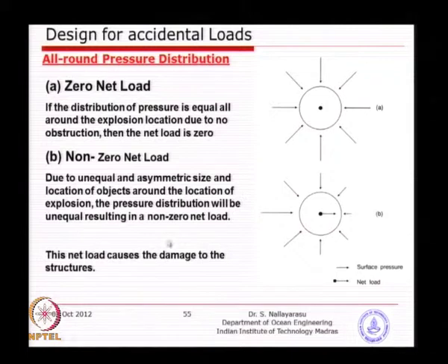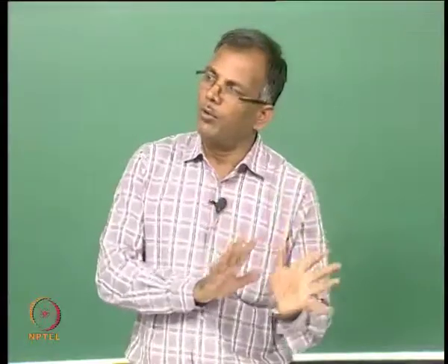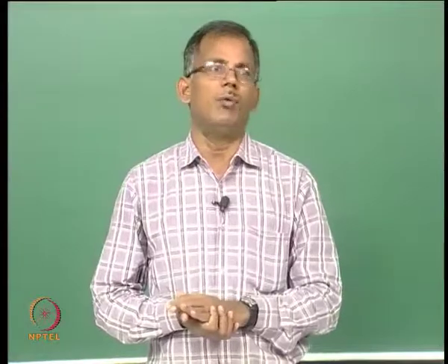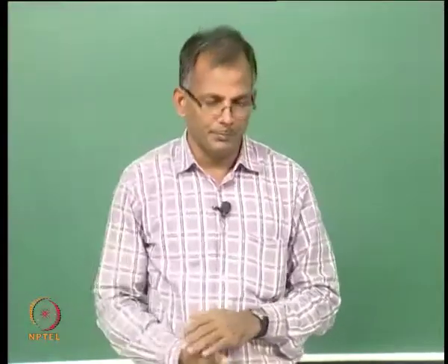That is exactly what happens in the real scenario, where the equipment and other facilities around a particular location of ignition and explosion are definitely not going to be uniform. There is no point in doing that. That net load causes damage to structures by trying to rip off the structure in the local vicinity, or the whole thing can go and impinge onto a neighboring wall or a bigger obstruction.